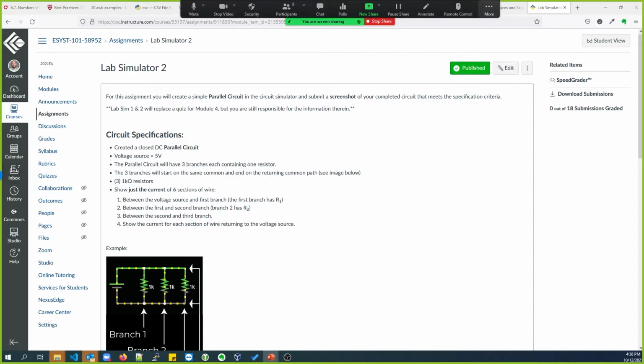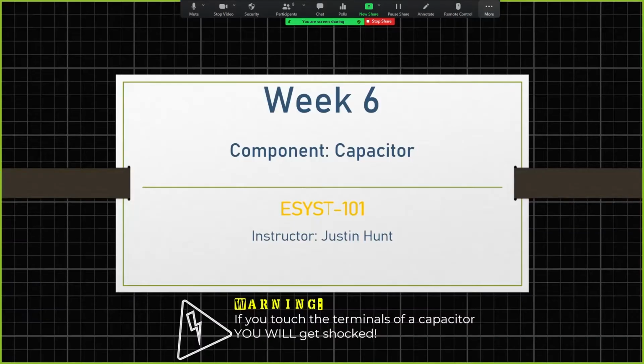Talk about the capacitor. Ooh. All right. Full disclosure: don't touch a capacitor if you don't know if it has voltage, or if you don't know it's live. Even if the circuit is live, it could still kill you. You know what, I'll do a demonstration video this week sometime of me discharging a capacitor and not blowing myself up. That'll be fun.